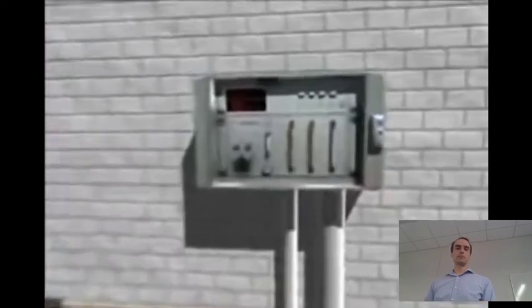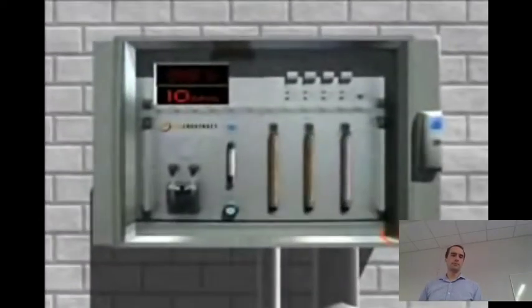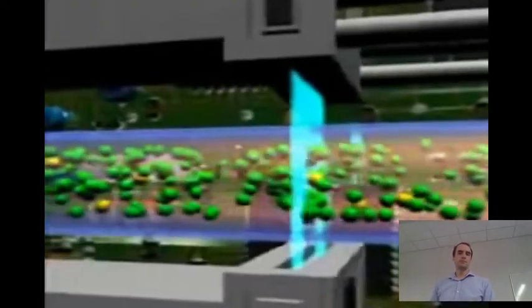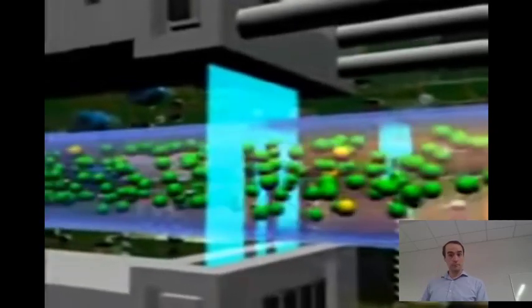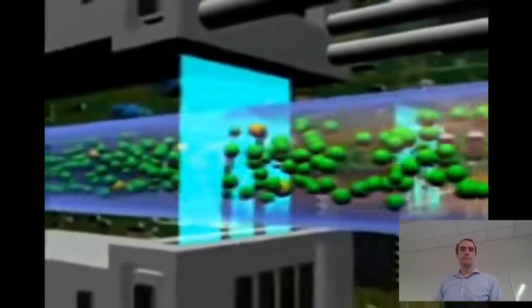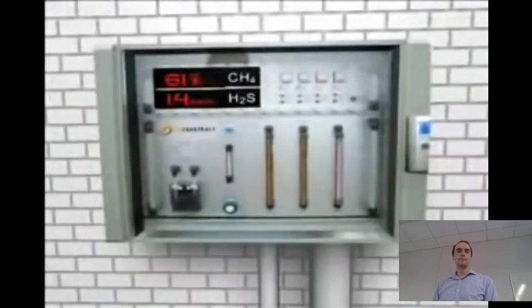This is carried out with the vapor at almost freezing point so that the gas is cooled down to a temperature of under 5 degrees centigrade. In order to control the purification of the gas, the biogas is constantly tested with an online measuring system, which records the amounts of methane, hydrogen sulfide, carbon dioxide, and oxygen. This guarantees a high degree of efficiency and security.